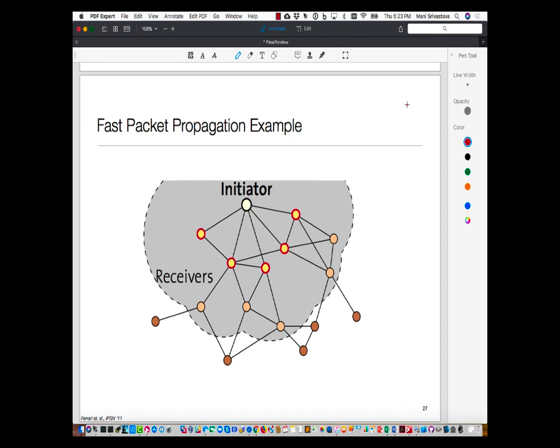The one condition under which it's not true is they transmit exactly the same thing at exactly the same time. To be more precise, they transmit such that the receiver would get them simultaneously. So let's assume for the moment they're equidistant from the receiver. They transmit at the same time with absolutely identical content. Then the interference pattern will just literally overlap and the receiver would still be able to hear. And then there are more sophisticated versions where I may know something about what the other party is sending and subtract it out. So there are fancier ways of making use of this.